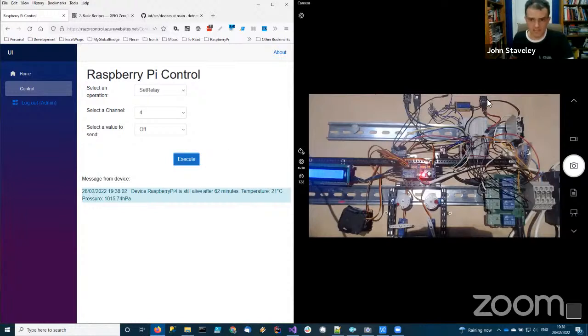Okay, so what was happening there? Every quarter of a second, my Raspberry Pi was asking, has the state of the button changed? Has the state of the button changed? If it detected a state change, it would then push a message up to IoT Hub.